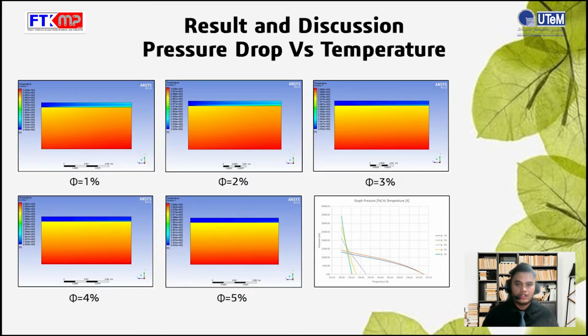Water CuO concentrations of 1% and 2% exhibit nearly comparable temperature distribution. When applying the water CuO 3% concentration, the temperature changed and nearly the whole length of the microchannel was chilled. However, the temperature distribution of the water CuO 5% has entirely cooled across the cross-sectional area of the microchannel heatsink. The temperature distribution contour was affected by the differences in the physical parameters of each nanofluid.